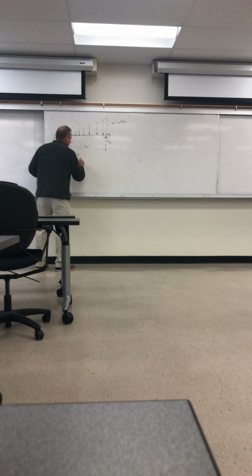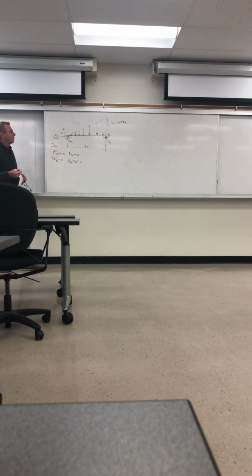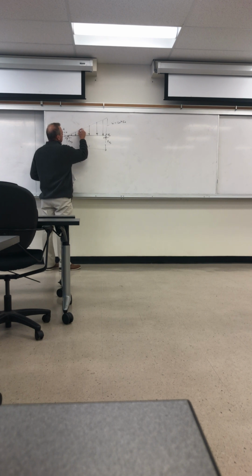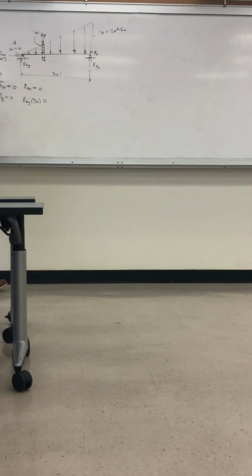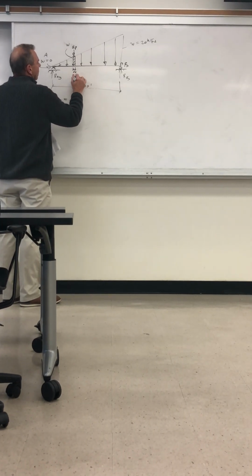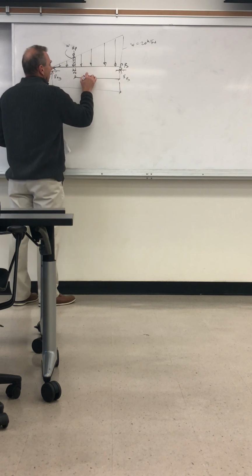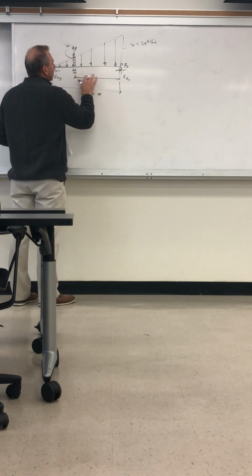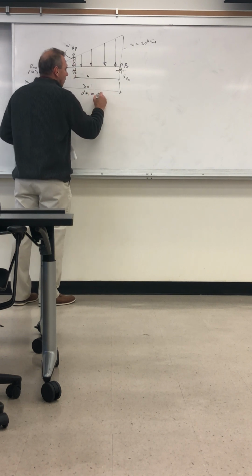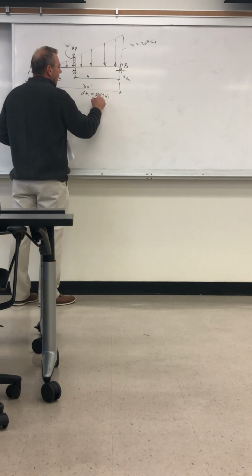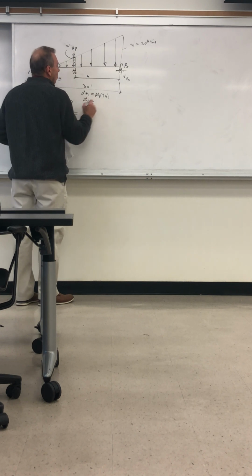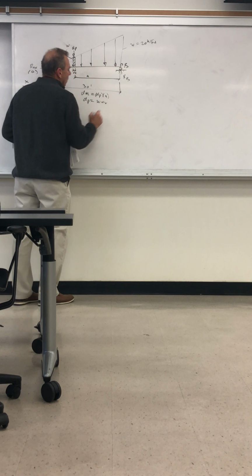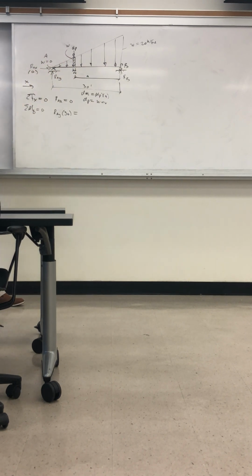And then that equals, and so again, instead of last time when we integrated using calculus, we represented each one of these little pieces as dP, right? When we did calculus, this was dx. The intensity at any given point is W, given by an equation. And then the distance there we could say was the moment arm, let's call that A. So the differential moment dM was equal to dP times A, and then dP was equal to W times dx. Then we just summed all of those. We ended up with a basic integral that we can integrate. We did that last time.